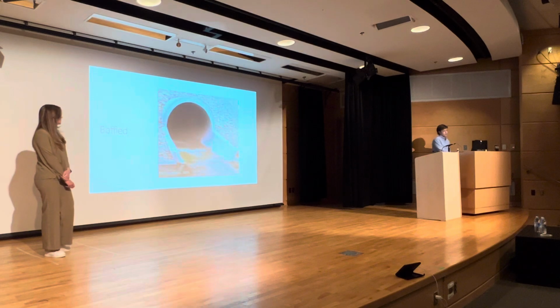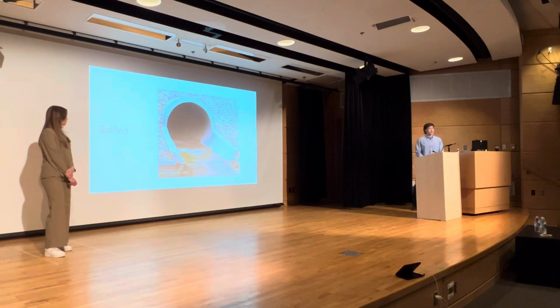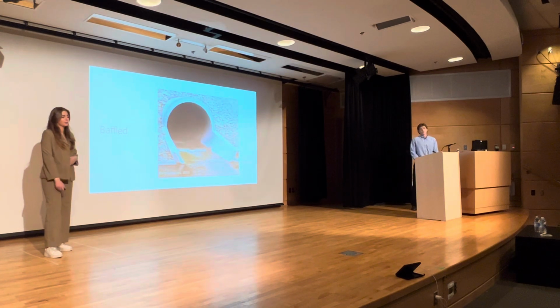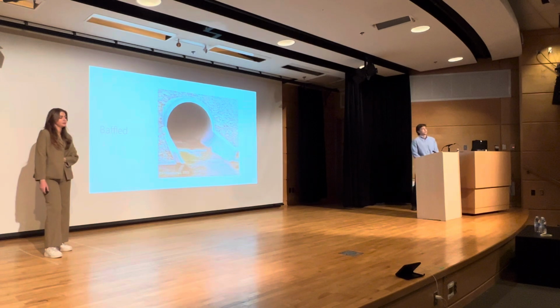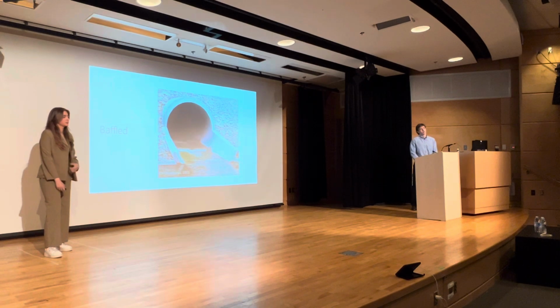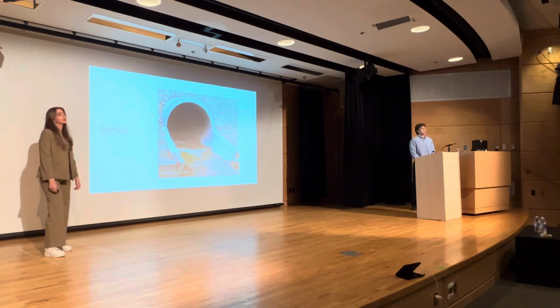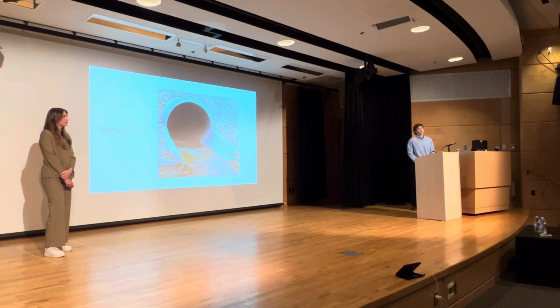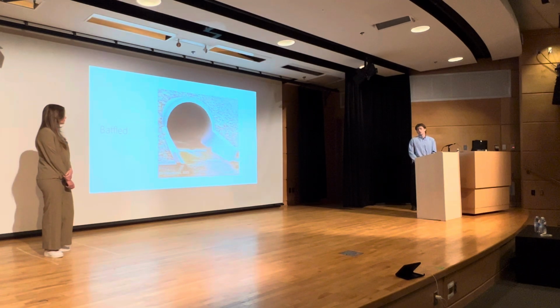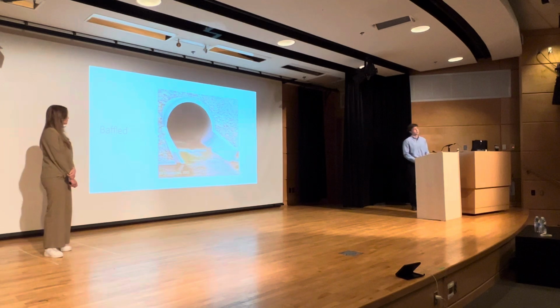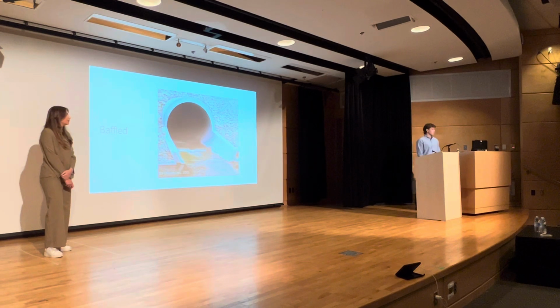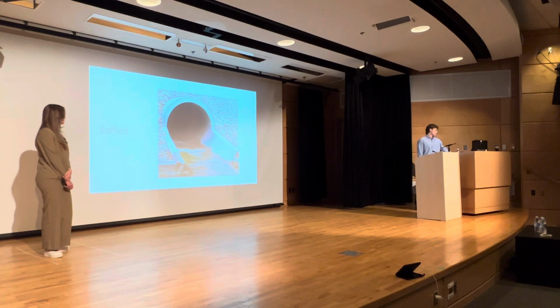And the final option is the baffled culvert. This is a great option for when we see slopes of river or stream beds greater than 5%, as this causes high flow velocities within these culverts. The baffles will slow down the flow through the culvert and create pools, which allows fish to jump from pool to pool to make it through their migratory path.